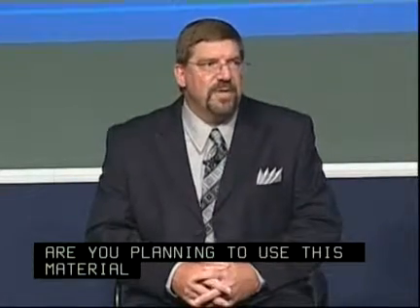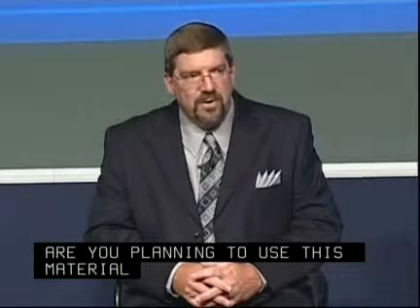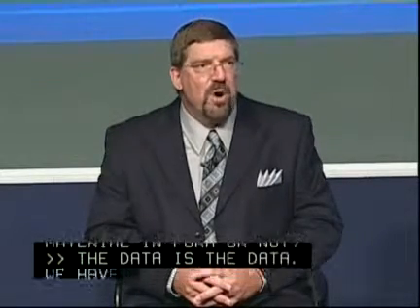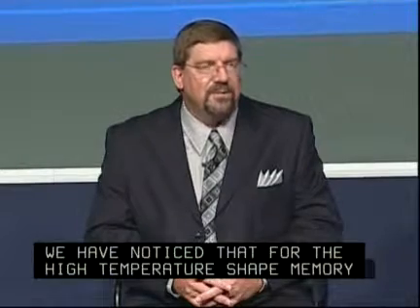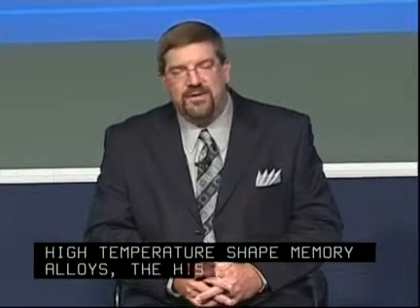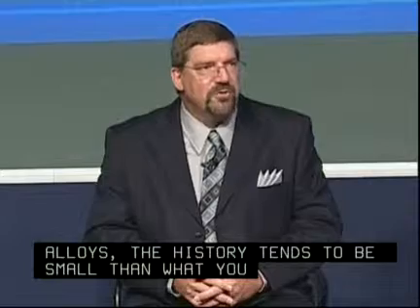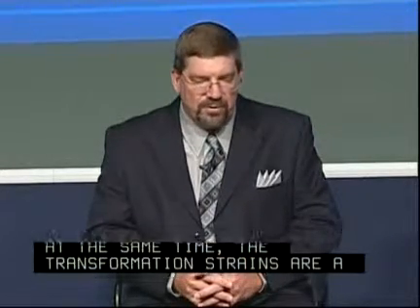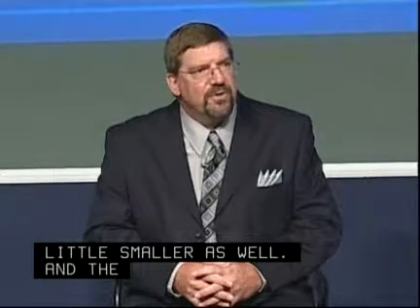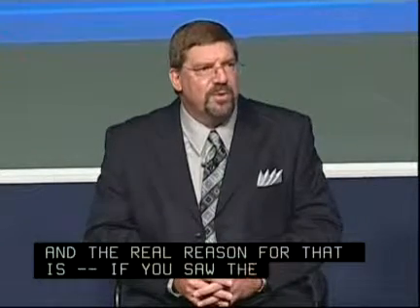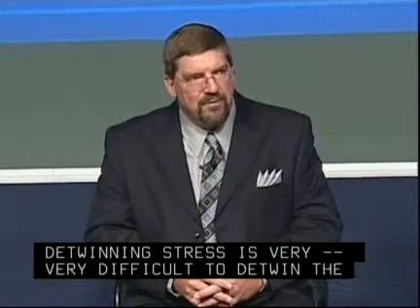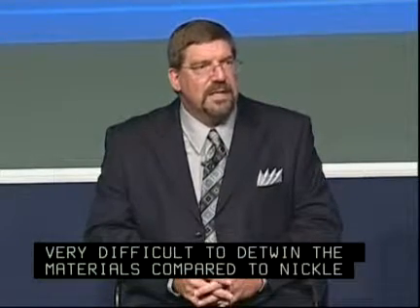In terms of what you see, the data is the data. We've noticed that for the high temperature shape memory alloys, the hysteresis tends to be smaller than what you generally see in binary nickel titanium alloys. At the same time, the transformation strains are a little bit smaller as well. And the real reason for that, if you saw some of the plots, is that the detwinning stress is very difficult. It's very difficult to detwin these materials compared to nickel titanium. You're looking at 50 MPa versus maybe 200 MPa. So you tend to get less